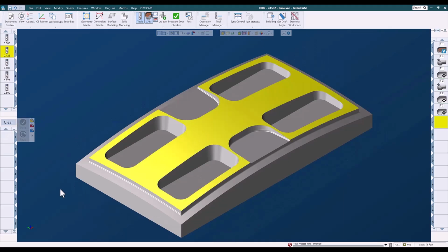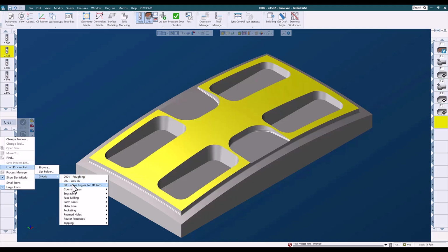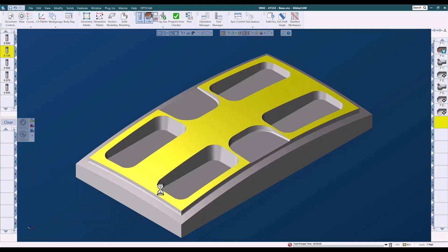So I think next we will deal with the top surface here. Let's find something for that. I'm thinking probably a geodesic, maybe offset from multiple curves, and it should be able to pick those up automatically. So let's right click, and I'm pretty sure I've got one of those. So we're going to go to 5-axis, geodesic, and parallel to multiple curves, automatic with a 1/2 end mill. That's not going to work. Let's go with a 1/2 ball mill.